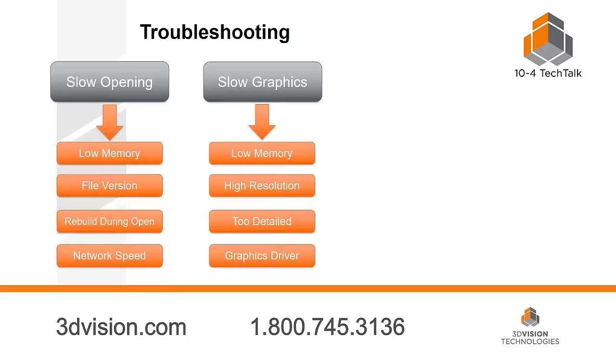If you have slow graphics, so you're trying to zoom in and out and it's being slow, here are some things you can look at for that category. You could, again, have low memory. You could be at too high of a resolution. Your assembly file could just be too detailed in general. You have too many components in it. Or your graphics driver from that first slide could be out of date, and you're going to want to upgrade